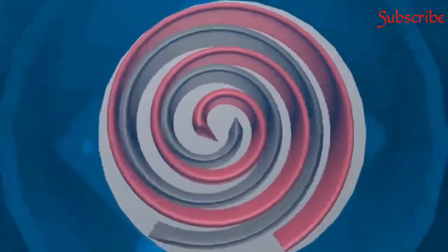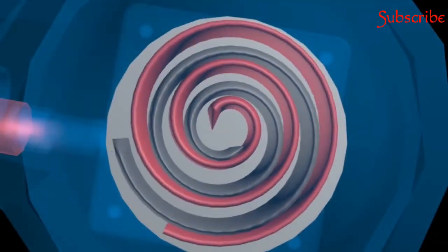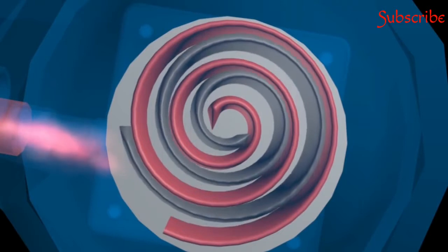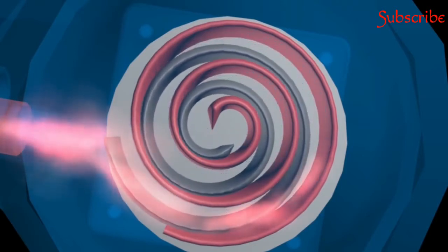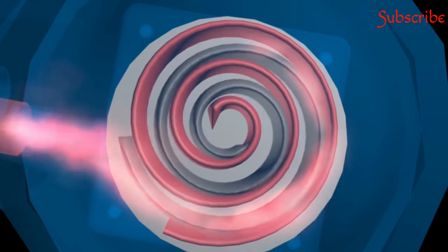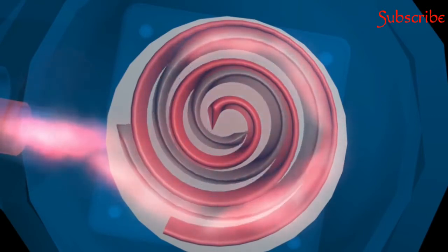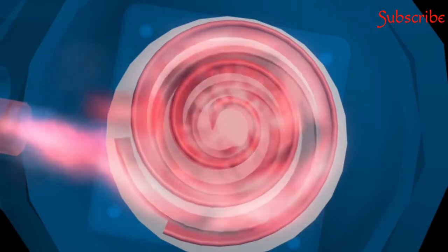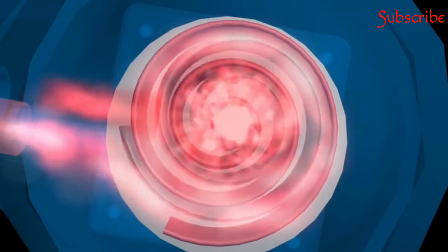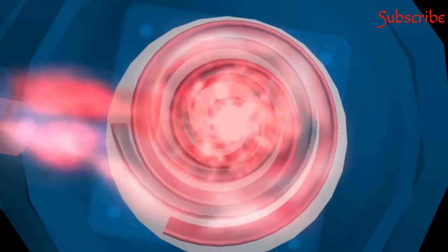The type of compressor used is scroll hermetic type. Scroll compressor works as follows: gas at low pressure and temperature enters the suction line and goes into the compressor. The low pressure and temperature gas is pressurized by the scroll compressor to high pressure and temperature gas. The high pressure and temperature gas is then passed through the discharge line and goes into the condenser.